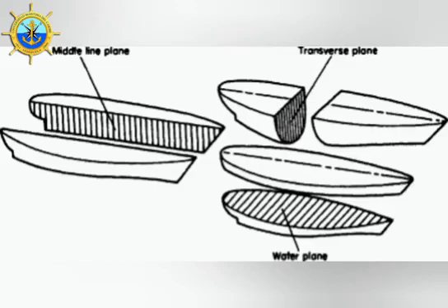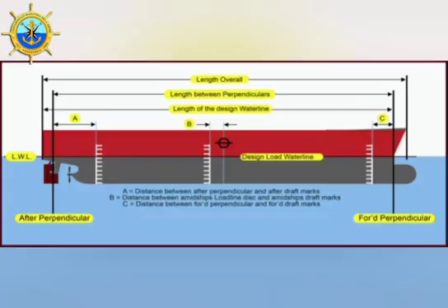The beam, which is the width of the ship, is not constant throughout the entire ship. The center line is the line resulting from the intersection of the diametrical plane with the transverse plane. It acts as the ship's axis of symmetry on which the transverse coordinate of the starboard or port side is measured. And the baseline is the line that we project to indicate the lowest point of the keel of our ship. This line we will represent in the longitudinal view and in the frame box.